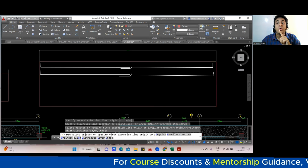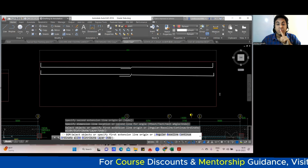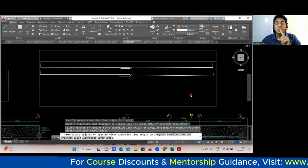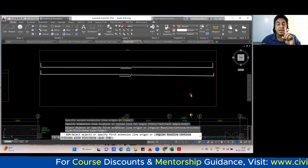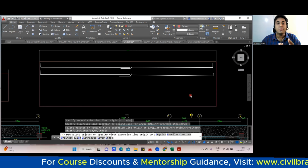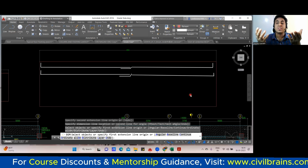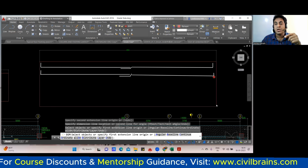Why? We know one thing. Whenever you do the execution, we need to understand not more than 50% of the bars has to be lapped at one section. What do you mean by that? If I have 10 bars and in all the 10 bars the lapping is coming. Here, how many bars did we get?